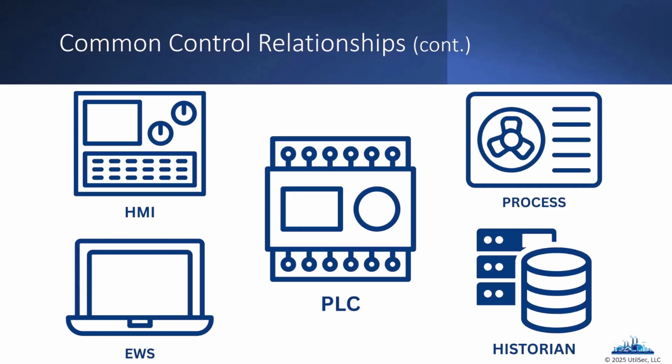It can be connected to by an engineering workstation to do things like upgrade firmware or make changes to programming logic. And then we can use, as operators, the HMI to see what's going on in the memory of the PLC, because that shows us what's going on in the process in the real world. And we can also make changes to the memory in the PLC to make changes that are reflected in the real world.